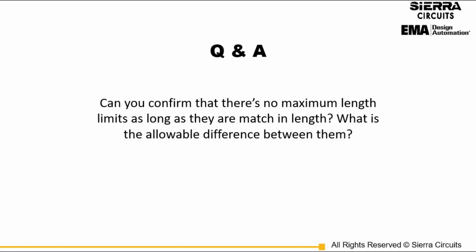You might be taking that signal off the board through a ribbon cable. If that's the case, length becomes an issue. So it all depends on the design, and definitely go back to simulation and simulate that board with the other boards plugged into it for that quality of signal. But short as possible is the goal, whatever you do.